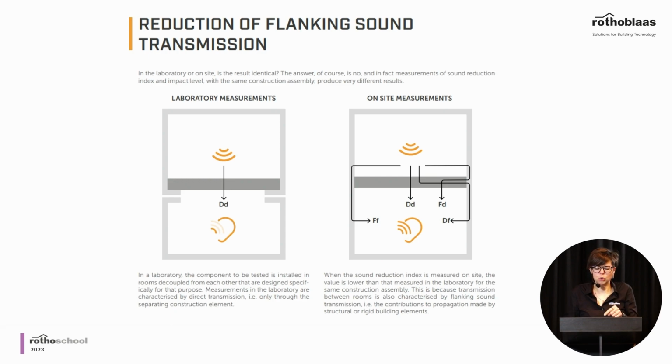So what happened, and you can see that with these arrows, if a side wall is vibrating, the vibration of these side walls will propagate to the other side walls on the other side of the separating wall, and this vibration will enter in the receiving room. So we will not hear only the sound produced directly by the vibration of the separating wall, but also produced by the side wall that is vibrating due to the contact with the wall, which is in the other room.